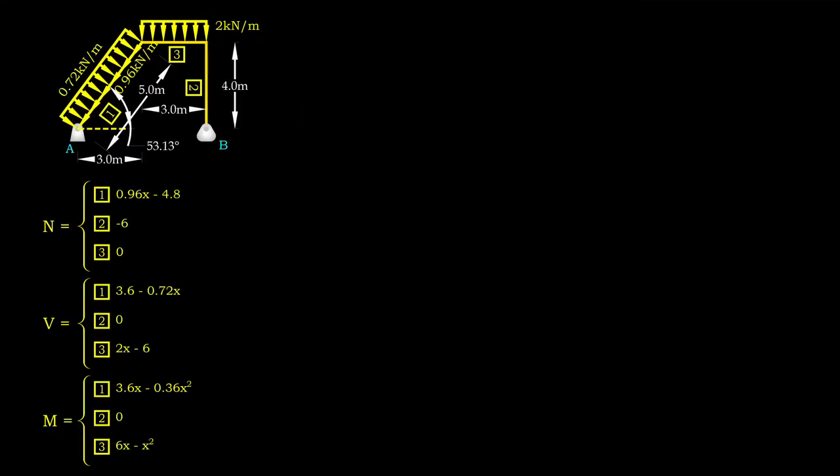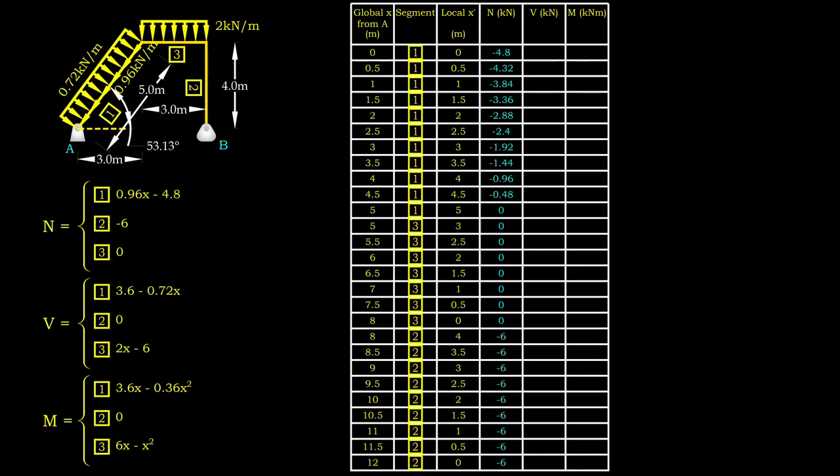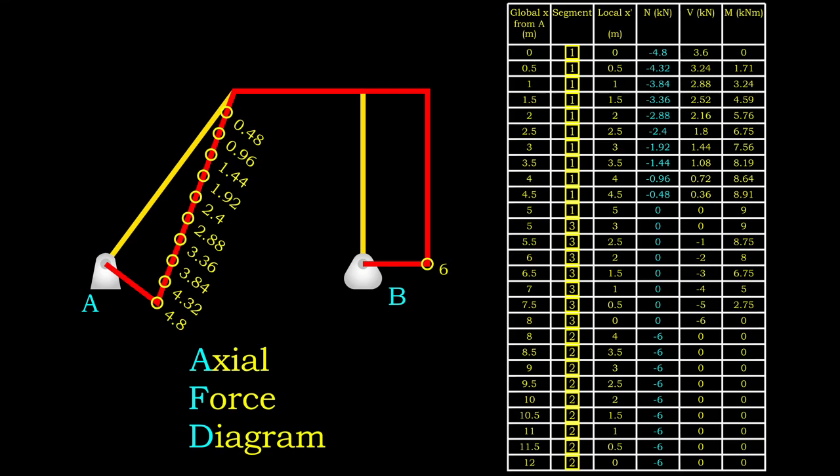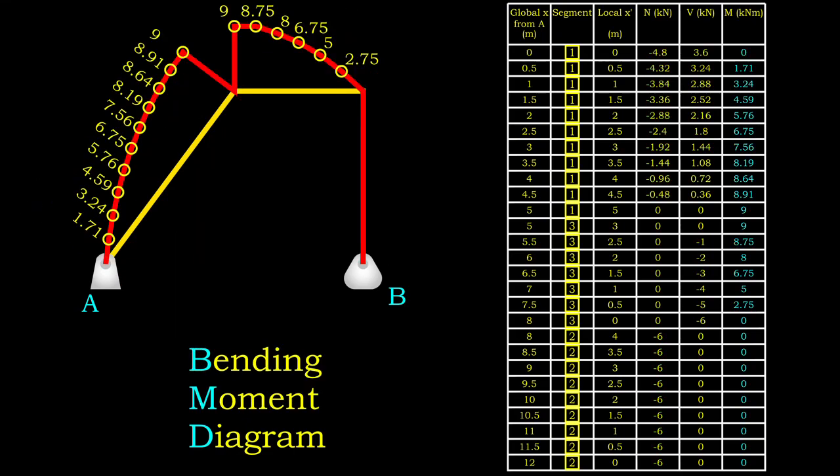With the internal force functions we develop for all segments, internal forces in structure can be calculated for every 0.5 meter interval. Then, we plot the axial force, shear force and bending moment diagrams on the structure.